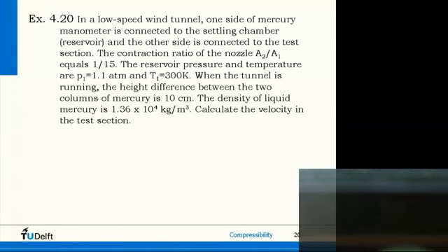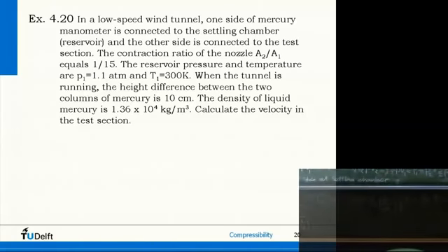Yeah? And this is how velocities are actually measured. So if you know pressure differences from manometers or pitot tubes, as I will explain in a minute, and you know contraction ratios, so areas, and somewhere a density for incompressible flow, you're there. You can apply this relation from Bernoulli and find it.